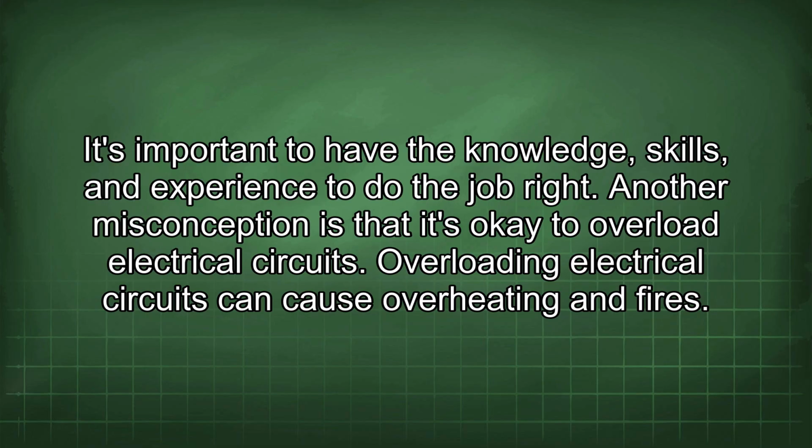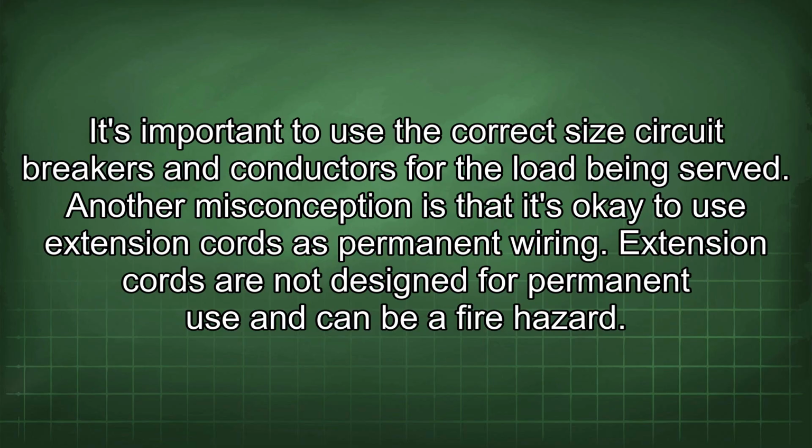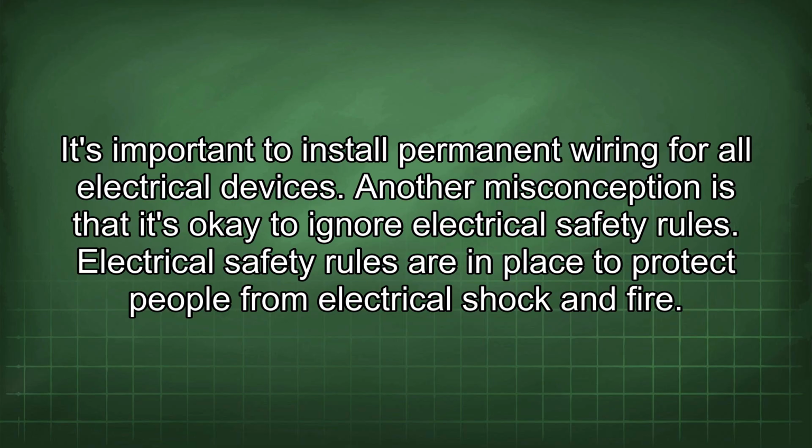Another misconception is that it's okay to overload electrical circuits. Overloading electrical circuits can cause overheating and fires. It's important to use the correct size circuit breakers and conductors for the load being served. Another misconception is that it's okay to use extension cords as permanent wiring. Extension cords are not designed for permanent use and can be a fire hazard. It's important to install permanent wiring for all electrical devices.